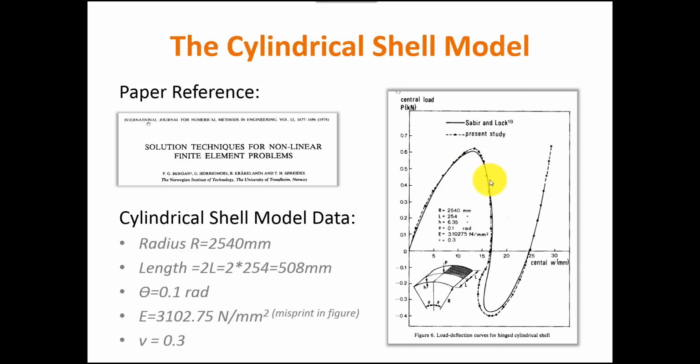And then the stiffness becomes negative, and in this area it's actually infinite negative, and then it turns in the turning point and becomes infinite high or positive. And then it snaps back before it absorbs more force again, and we have this behavior after the last limit point. You can tell that there are two singularities here.